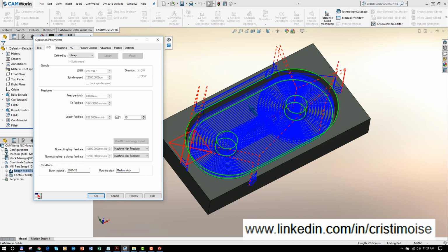It is on, of course, when you define the VoloMill pattern. A non-cutting feed rate, as I told you earlier, the VoloMill algorithm has a different and enhanced algorithm. Because VoloMill uses high-speed speeds and feeds, avoiding drastic changes in direction and sharp corners is recommended in order to prevent wear of the tool.